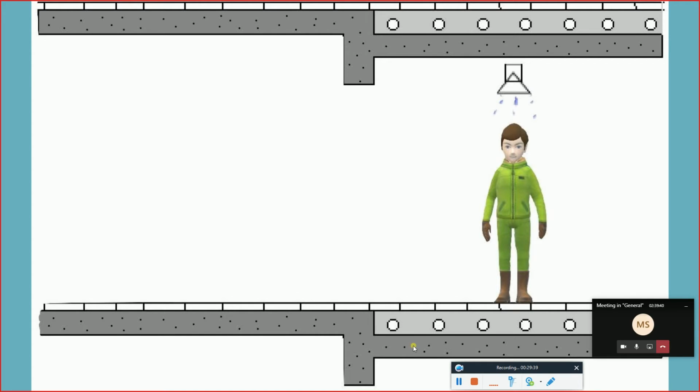I need to sink this particular slab down so that the pipes and the connections are going to be made, and then finally the level of the floor is going to be the same. I don't want to see that my bathroom or my toilet is having an elevated level compared to the regular level, and that will cause you as well an issue in terms of water drainage.